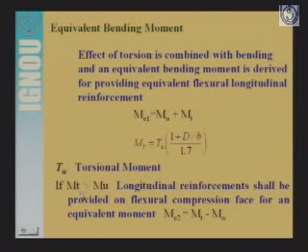Here if Mt is greater than Mu, then longitudinal reinforcement shall be provided on the flexural compression face for an equivalent moment of Me2, that is Mt minus Mu.